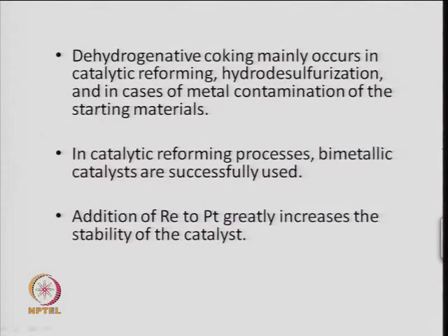So, here the dehydrogenated coking mainly occurs in the catalytic reforming. So, reforming catalysts are very much prone to coke formation, a large amount of coke forms. So, the catalyst life drops faster. Same thing for the hydrodesulfurization also, because feedstock itself contains a lot of coke precursor, and in cases of metal contamination of the starting material, because as I said, the metal continuously deposits on the surface of the catalyst, that is again a fouling.